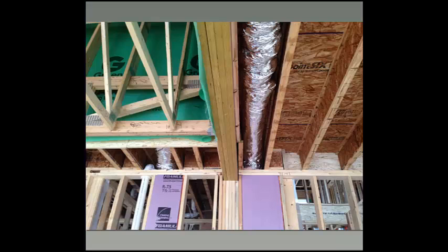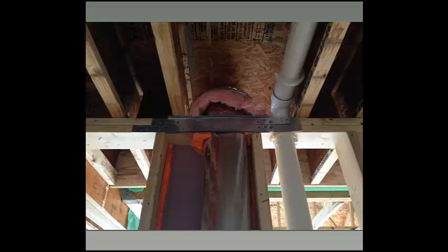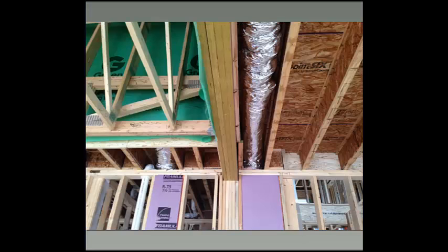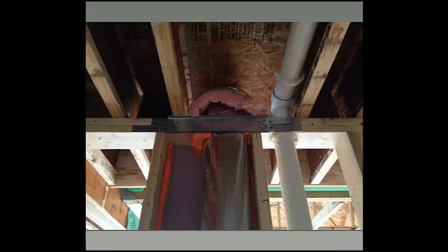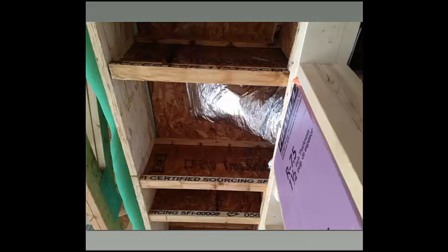In this example, you can see a contractor using some oval duct. Let's see, yeah, there's the oval duct in an exterior wall, but they used R7 foam insulation to theoretically bring that duct inside the conditioned space. But some code officials may not be on board with that, since you don't have full cavity R value in that space. So again, you really are going to want to work with your local official to determine what's inside and what's outside.